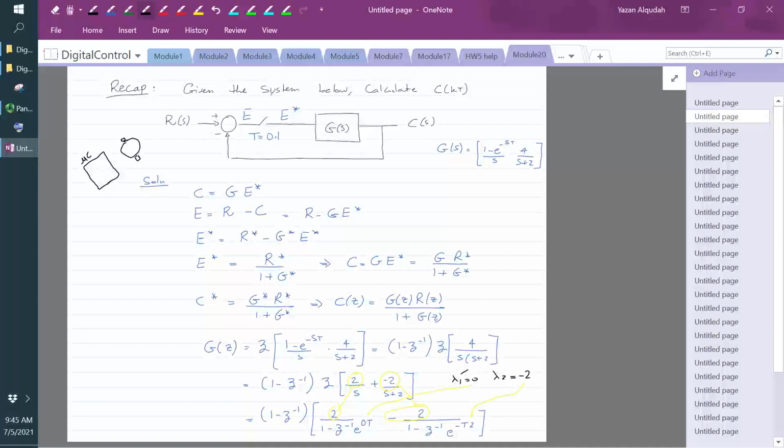I'm taking the difference between where I want the position to be and the current position, and subtracting them from each other. So let's say I have an op-amp that subtracts the two signals, the output and the input.